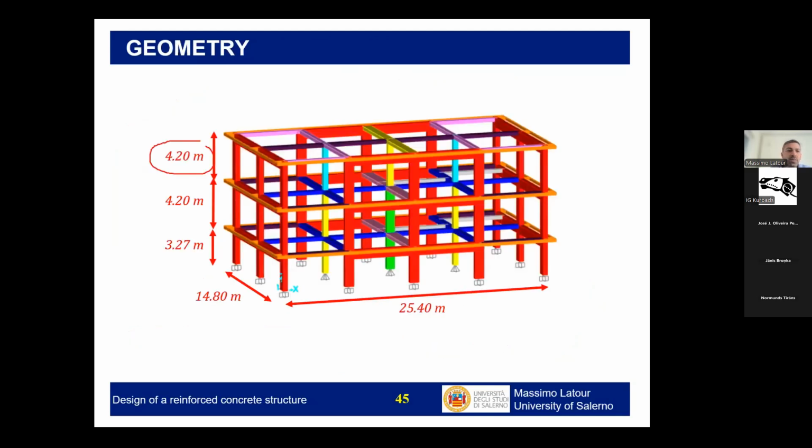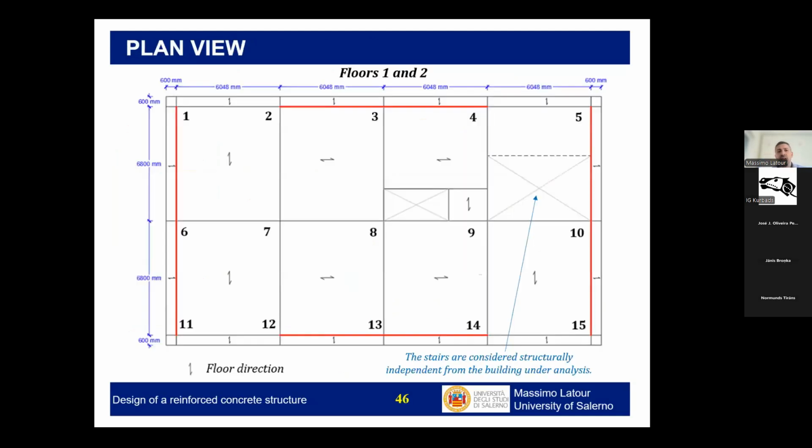So these are the geometrical characteristics of this structure in height. Let's say that, I'm not reporting explicitly the checks, but based also on the layout of the structure that we decide to realize, the structure will show to be regular in plan and elevation, so that we can apply the equivalent static force method, so the lateral force method provided by Eurocode.